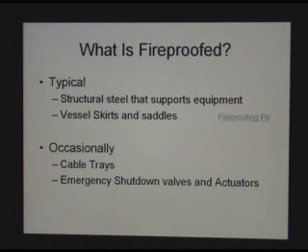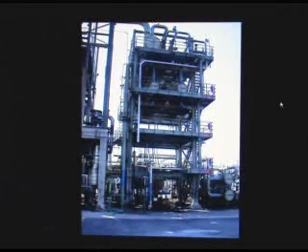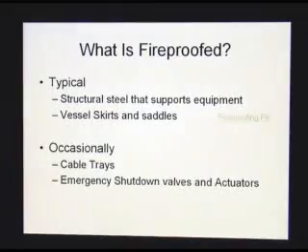We fireproof typically structural steel that supports equipment, and vessel skirts. Click on the link, please, on the fireproofing picture. Oh, it's bad. But this structure is only partially fireproofed, but you can see that the entire column here is fireproofed up to the top, and the cross members are fireproofed here.